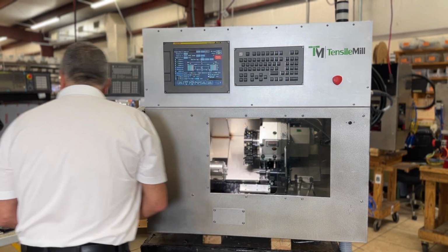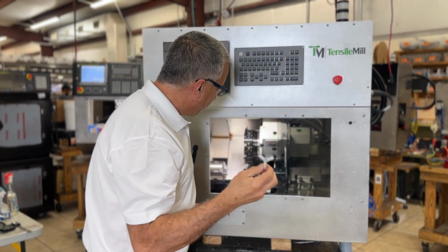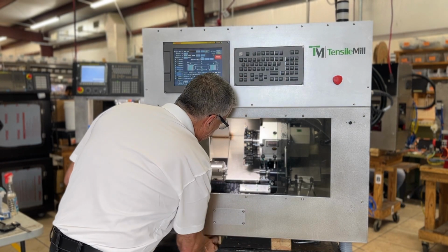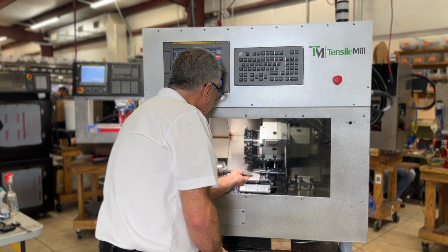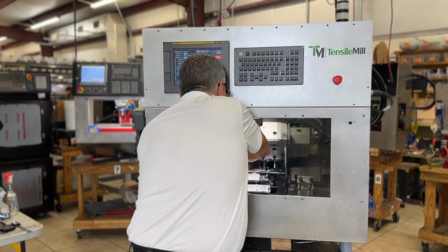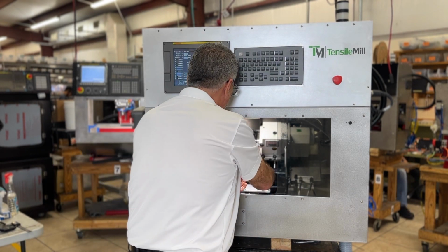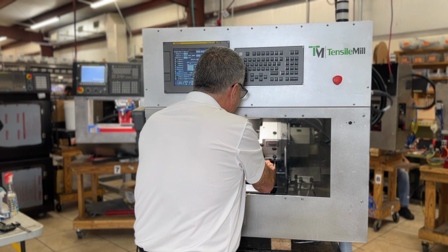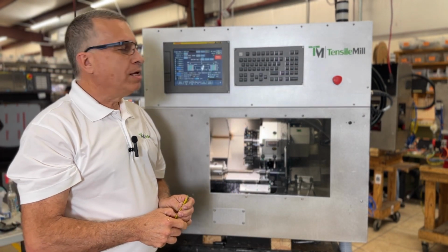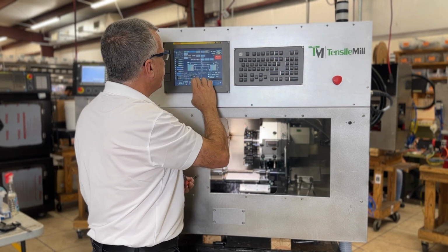In fact, I'm going to put a stopper. I use this little stopper to prevent the part from going into the chuck. And I just bottom it out on the stopper. Make it tight. Then I can measure here. So it's 5 inches. Whatever value I have there, if it's 5.1, 4.9, I will specify on the program. So I put on the program 5 inches.